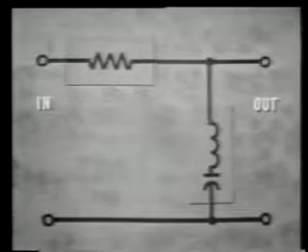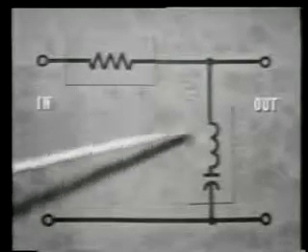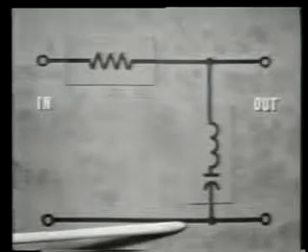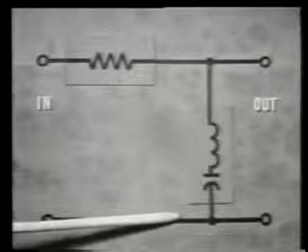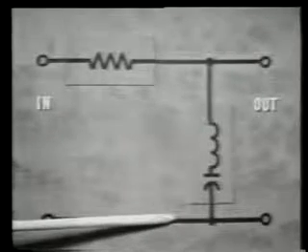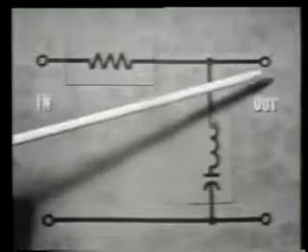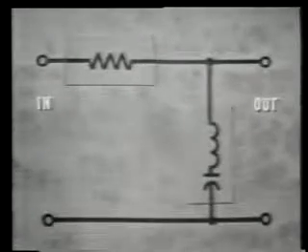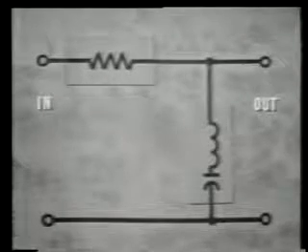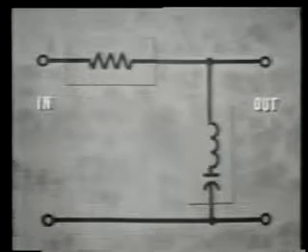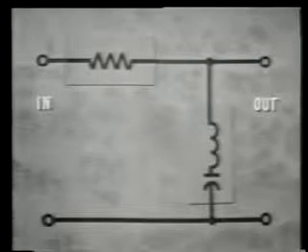At frequencies above and below resonance, however, the tank opposition now becomes maximum. Now if the tank opposition is maximum, it then will develop the maximum voltage drop across it. So at frequencies off resonance, the output voltage will be maximum. Thus, this filter configuration will reject frequencies right around resonance, but pass all others. Let's demonstrate this.